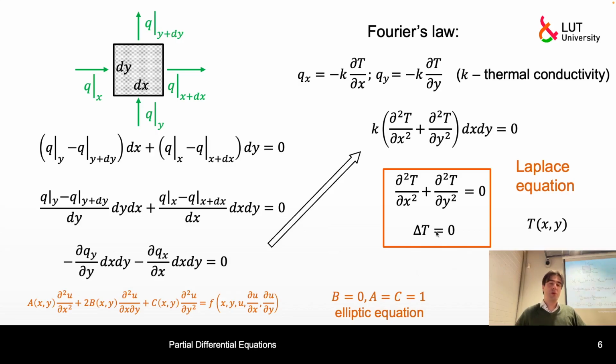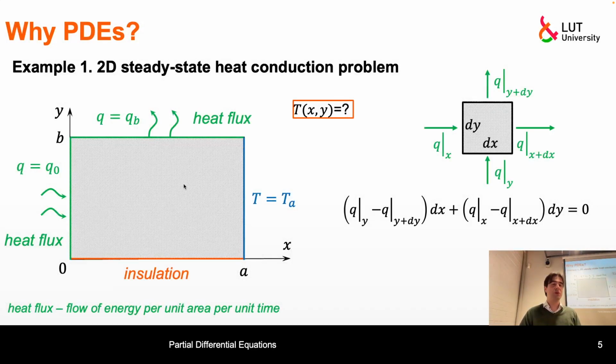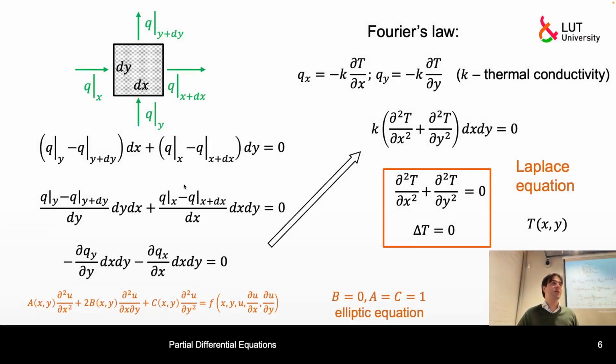So the short way to express this is using this Laplacian operator notation, this delta symbol. So it's just Laplacian of temperature equals 0. And from here we can find the distribution of temperature, but not yet, because you realize that there is nothing here about what happens on the boundaries, which in our case actually defines the distribution of temperature. Otherwise, the obvious and the only solution will be just 0 temperature everywhere. So it's important that we will have to think about boundary conditions.